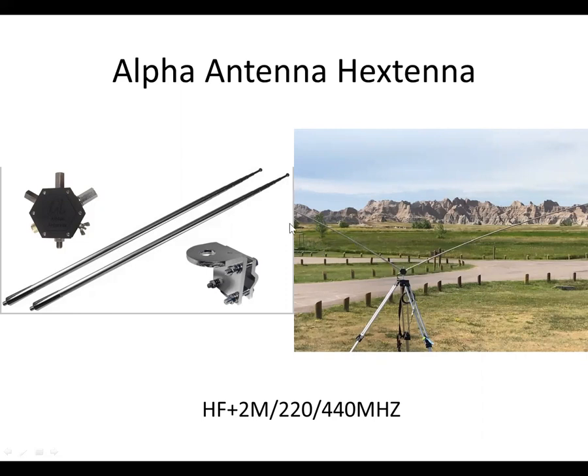But as soon as I looked at that, I saw that since these are telescoping elements, that antenna would be infinitely adjustable in length. So I could adjust the resonant point on any band exactly to where I wanted it just by adjusting the lengths of the 2 dipoles. So we ended up buying this thing.